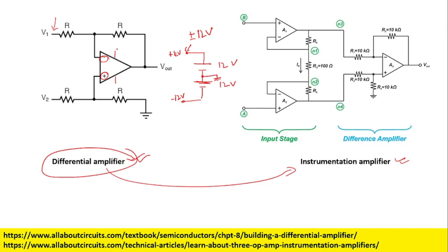So that's how, when we design an op-amp based amplifier, we have to power it with a dual power supply. This is a simplistic one, but we have electrical circuit based power supplies also, which can give you the dual power supply. The basic analogy is that you need two power supplies of similar specification connected together, and from the center tap you connect to the ground.